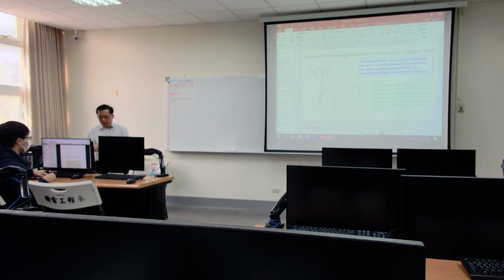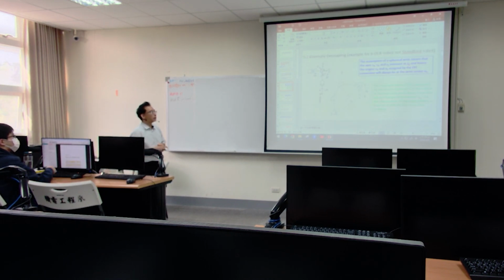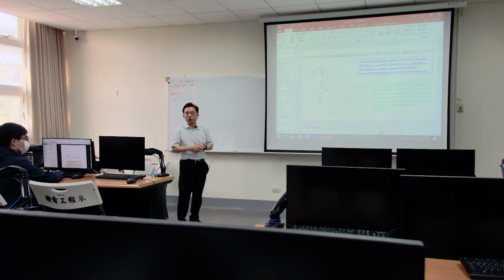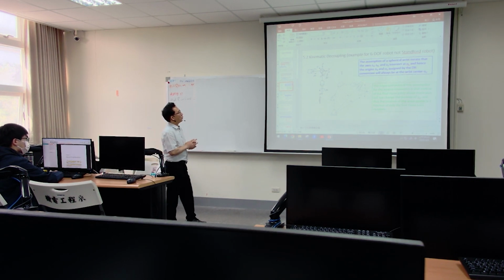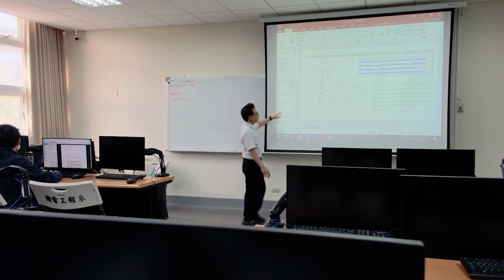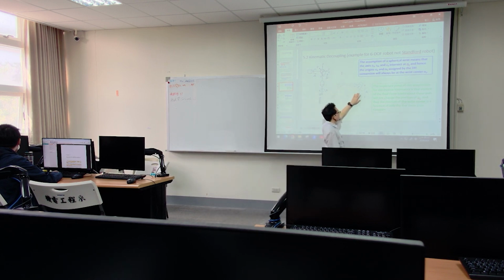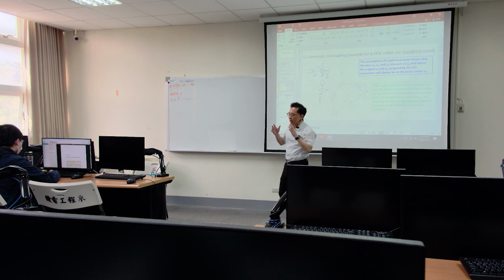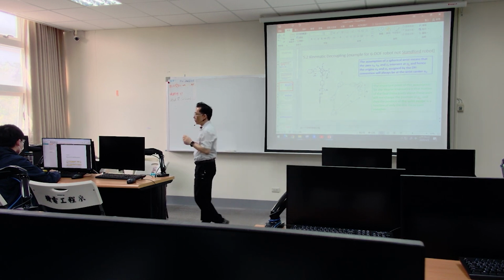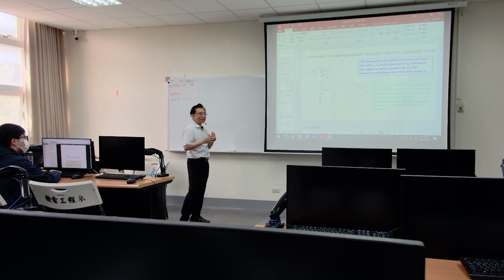Okay, so this is exactly the procedure we will use. We decouple the last 3 joints. We call it the wrist. I mentioned it before. I always use the same term. If I change it a little bit, remind me. I don't want to do that. So the last 3 joints we call the wrist joints. We decouple them from the first 3. This is the independent kinematic system.